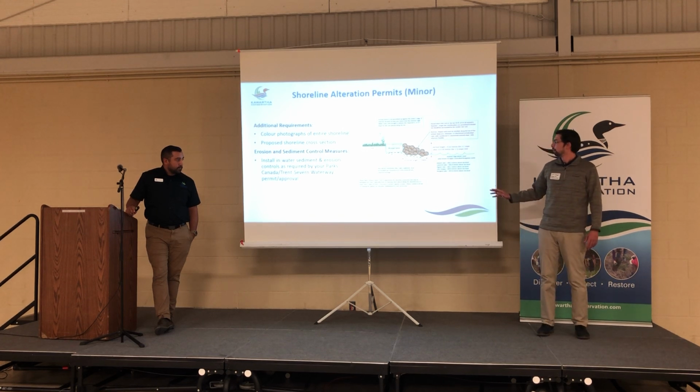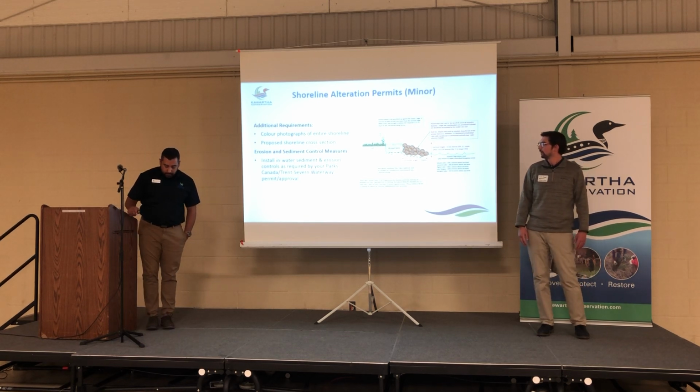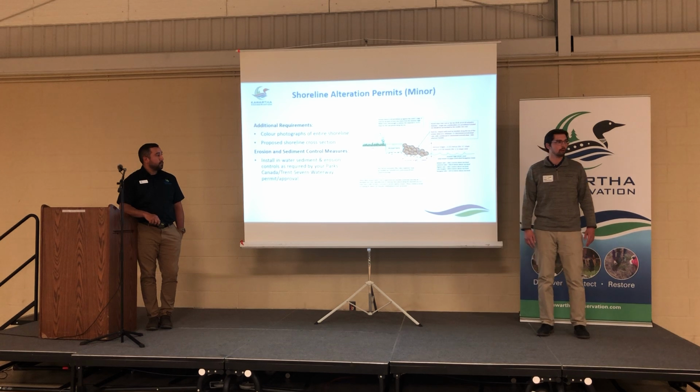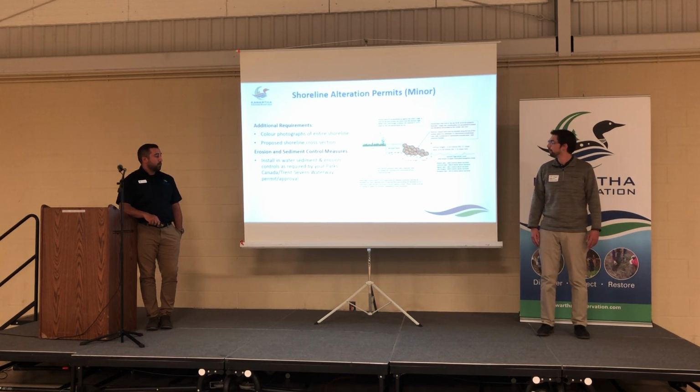Generally, we would put conditions on the permit that the armor stone is set back at least 1 meter from the high water mark, and that sloped rock is placed on a minimum 2-to-1, but 3-to-1 where feasible, slope.